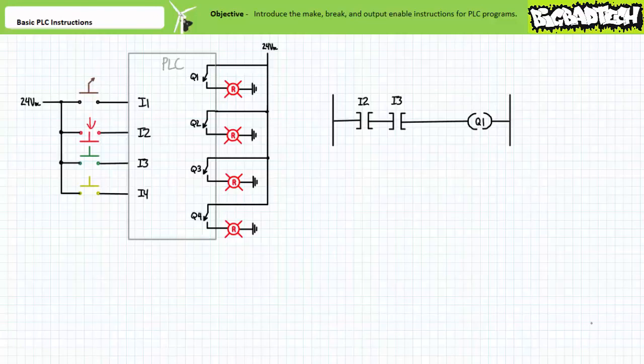This shortcut isn't really that far from the truth of how some PLCs operate. In order to minimize scan time, PLCs often turn back at the first locked door and only continue progress along a rung if logical continuity can be maintained. For this scenario, output Q1 is de-energized.